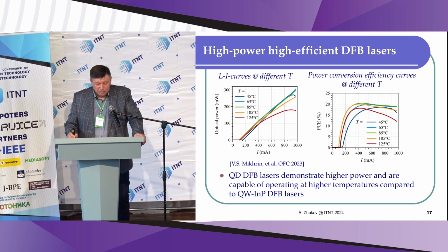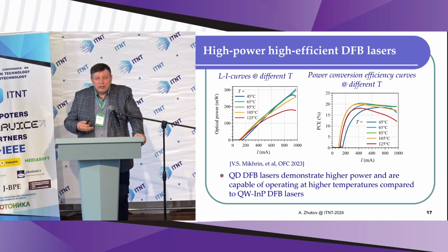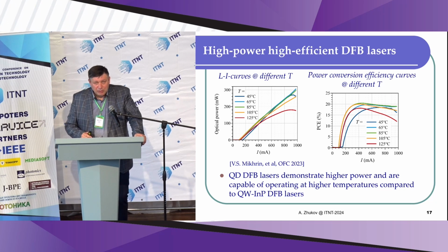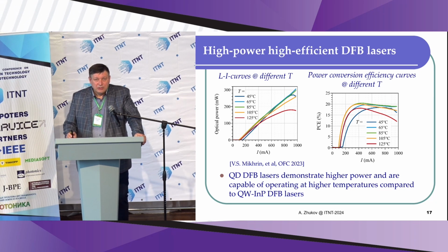And what is more important, single frequency operation is associated with very high output power and reasonable power conversion efficiency. So the power remains high even at elevated temperature, and the power conversion efficiency also remains high even if the temperature exceeds 100 degrees C.